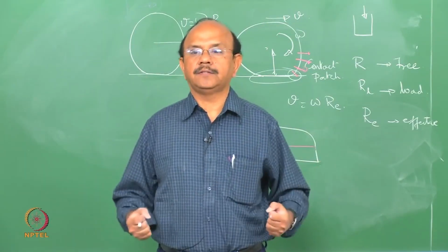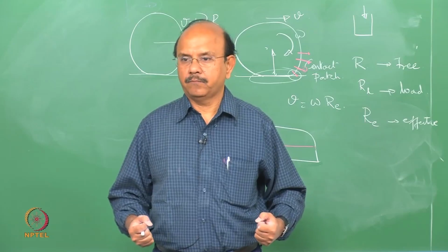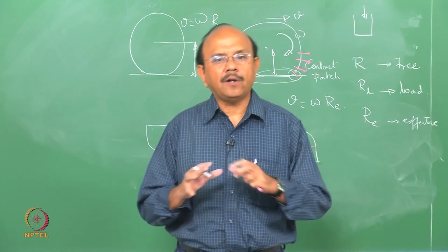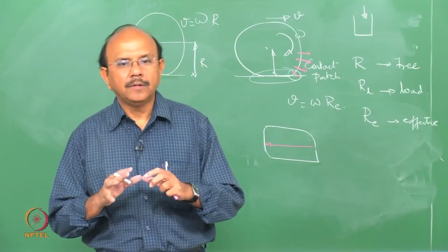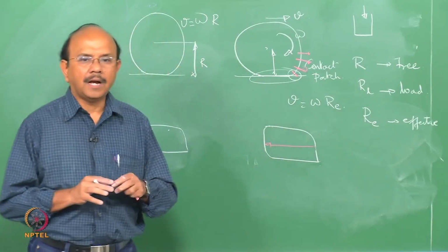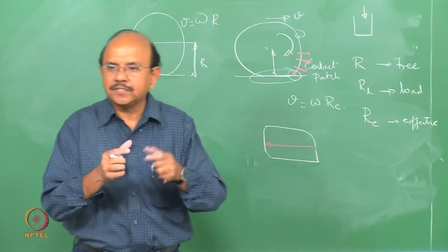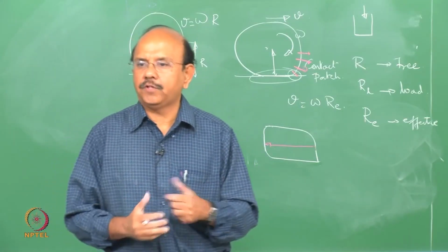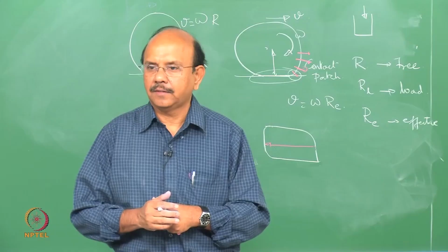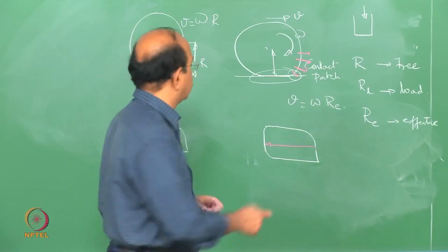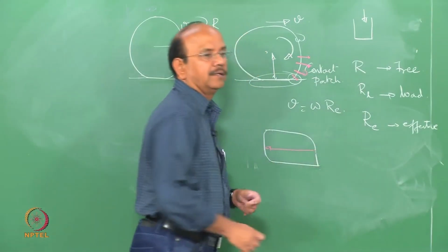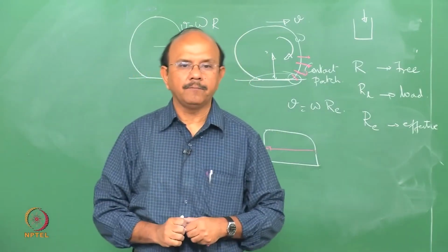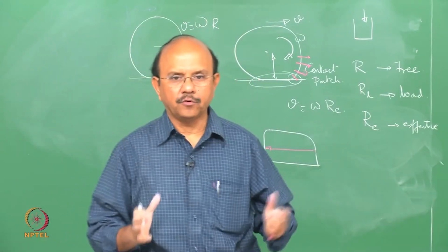So again I may stand here. So if at all I move in the contact patch, I move over very short distances, micro distance, micro slip. I do not slide from here to here. The contact patch, as I said, goes above me, and at the maximum I am going to just move like that.